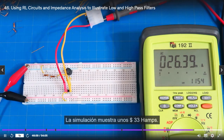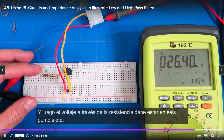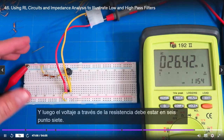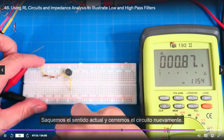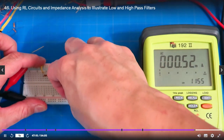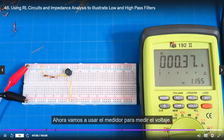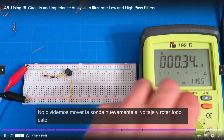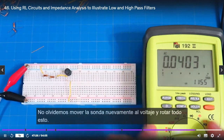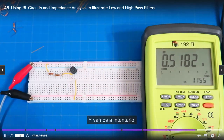The simulation is showing 33 milliamps. All right, and then the voltage across the resistor should be 6.7. So let's see if that's true. Let's pull out the current sense, and let's close the circuit again. All right, so the circuit's closed. Now we're going to use the meter to measure voltage. Let's not forget to move the probe back into voltage and rotate this thing all around. All right, okay, and let's give it a try.